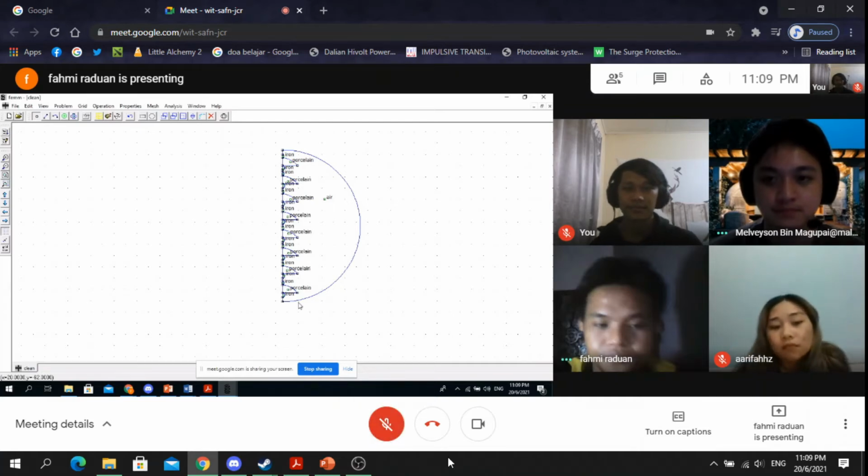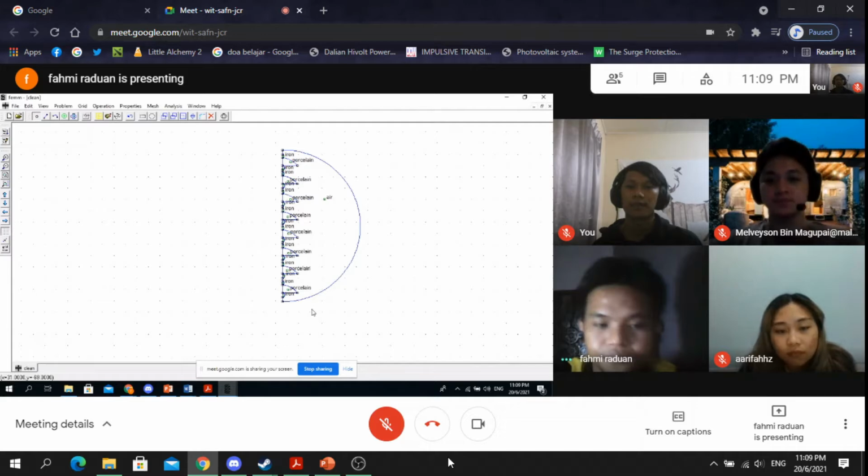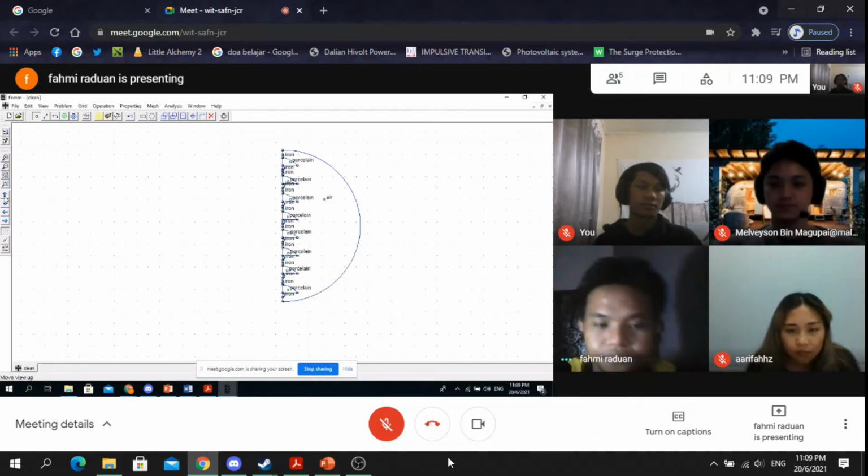Assalamualaikum, my name is Muhammad Fahmi. So we'll continue with FEMM simulations. For FEMM simulation, we do the 2D sketch in axisymmetric. So this is for the dry condition. For the dry condition, we have three materials, which are iron, porcelain, and air.